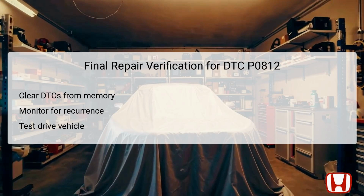Following the troubleshooting and any necessary repairs, the final verification process begins. It is essential to clear the diagnostic trouble codes, DTCs, from the vehicle's memory using the Honda Diagnostic System, HDS, to reset the system. After resetting, conduct a test drive of the vehicle to observe its functionality under normal operating conditions.